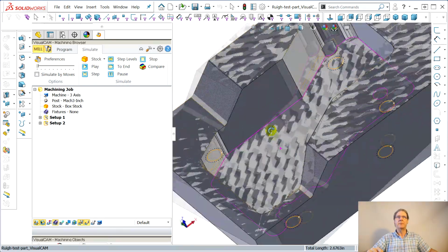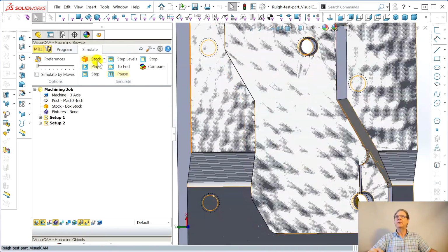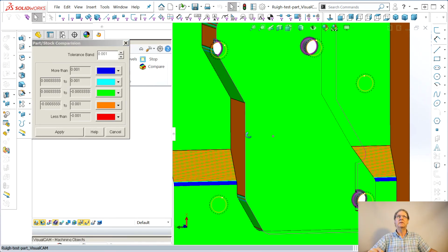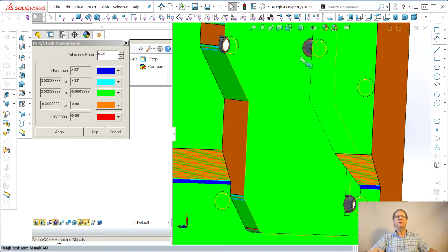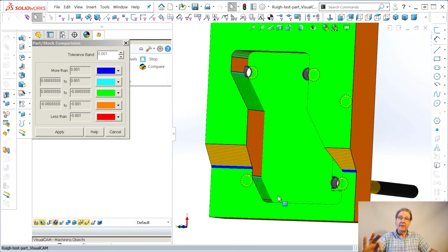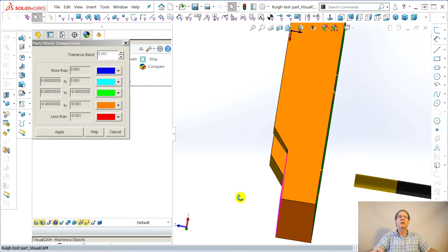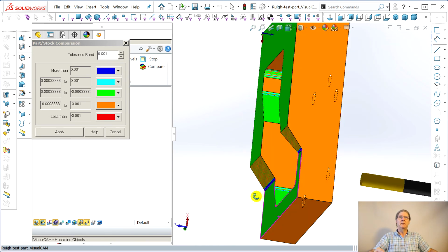Yeah. So there's our part. Got the through holes. You do the compares. Why is it leaving the gray? I mean, that should be a color, right? It should be blue or red. Maybe because it's a tap. They say, well, it would mislead you. That's pretty sophisticated because it showed up red in SolidWorks CAM because the tap is defined by the outside diameter. The hole that SolidWorks uses for the model is decided by the tap drill, the smaller inside root diameter of the tap. But this is all pretty good.